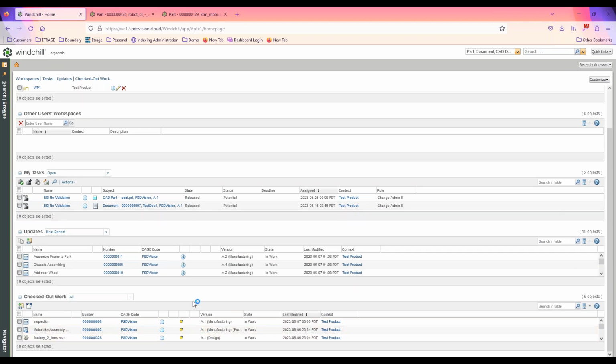And then the last table on here is just to show you work that's checked out to you. It might be that someone needs to work on this stuff, but you have checked out this assembly, and they don't have access to it because it's locked out to you. No one can modify it at that time. They can still see it, access it, open it up, but they won't be able to check it out and modify it. So they'll probably ask you to go in and check that file in before they could work on it. This is stored somewhere in the system in a folder, and I'll show you that in a bit. But if you're not sure where it is, you can simply come to this table here, and from here I can go to this particular file and check it in.